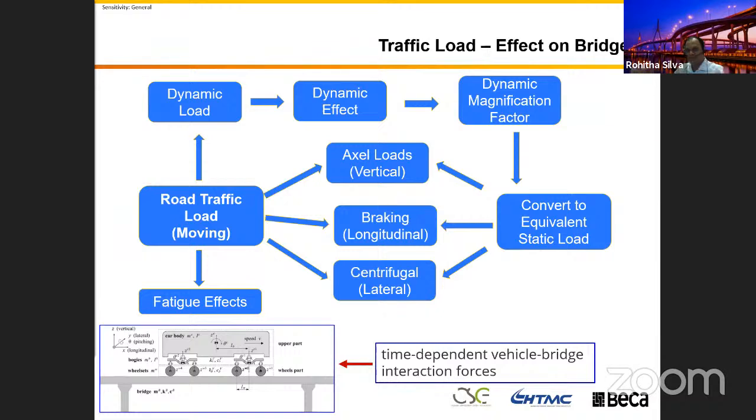In addition to that, I think we saw this slide before, when you put the traffic on the bridge, because the traffic is a moving load, the bridge is not that even. I think you got that experience when you are driving through the expansion joint, bang, bang, bang, that noise and that feeling you get yourself when you are sitting in your car. So this dynamic effect will induce additional stresses on the bridge.